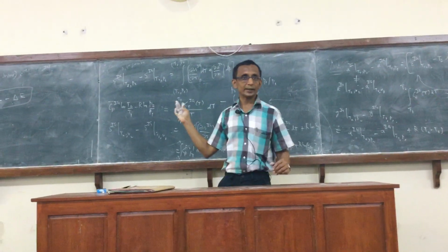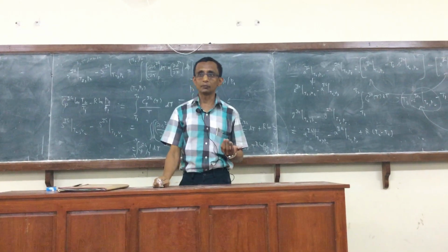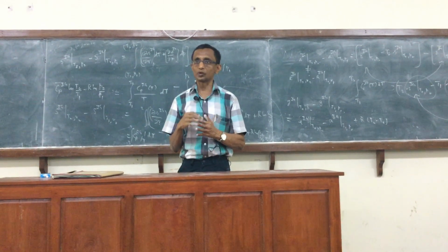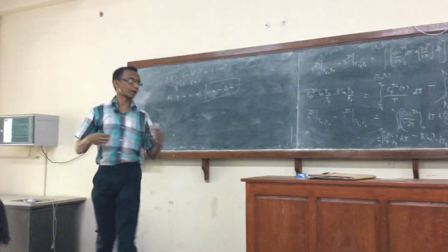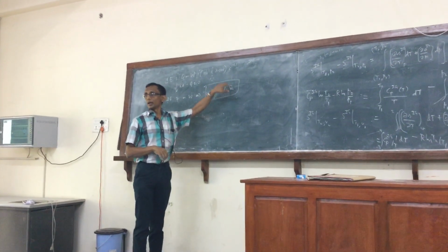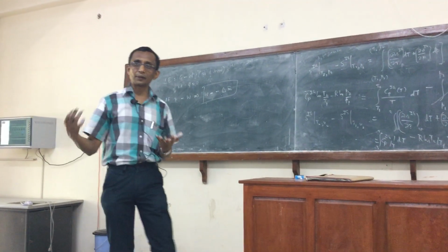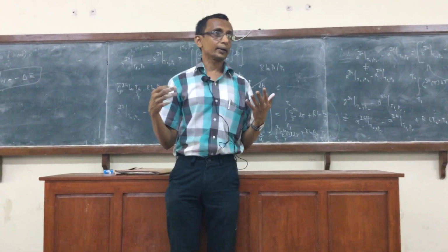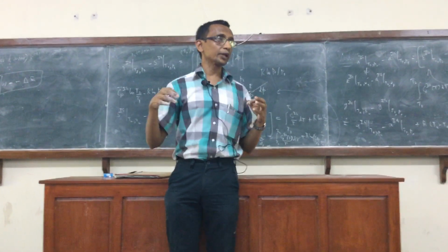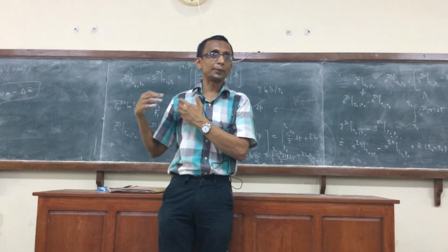So now what is the relevance of this to whatever we have carried out? We have seen certainly how to calculate delta of any property E. This is for a fixed amount of fluid, so if we calculate the delta for small e, or the epsilon, I can easily calculate this. Now the only assumption here is that the process undergone might be reversible or irreversible, whatever it might be, the details of the process are not important here, but it is important that the starting state and the ending state are both equilibrium states.